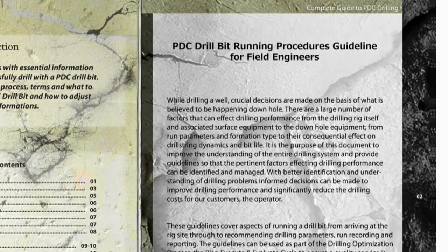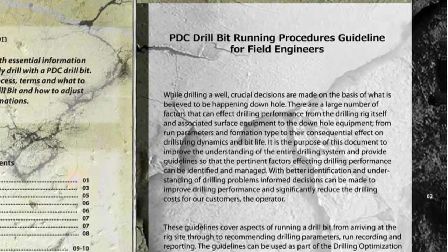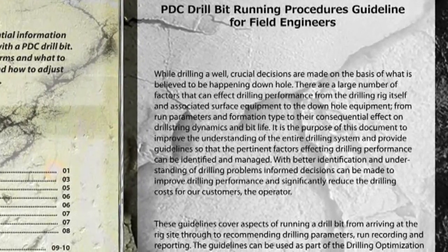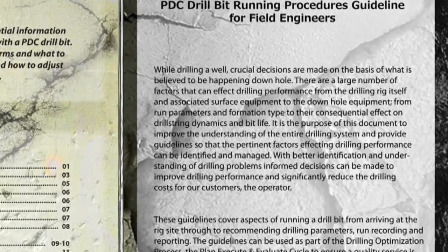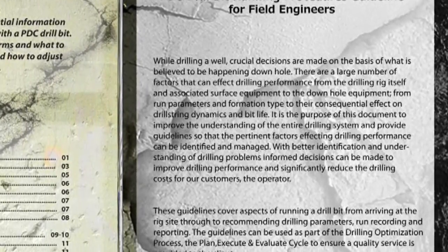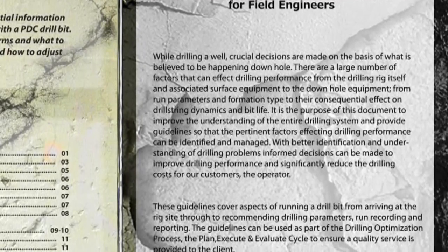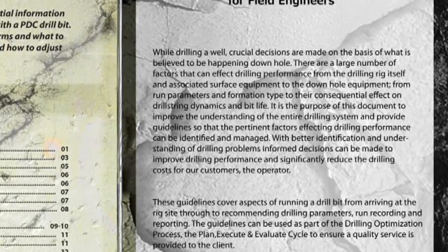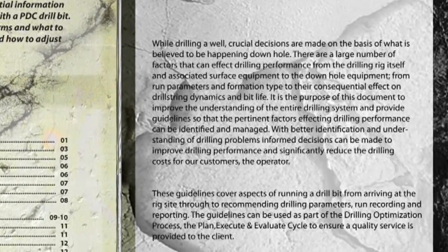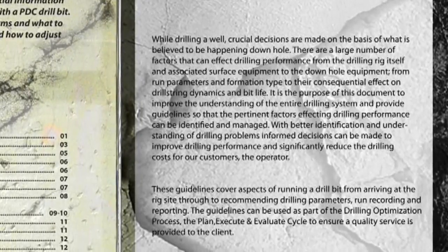PDC drill bit running procedures guideline for field engineers. While drilling a well, crucial decisions are made on the basis of what is believed to be happening downhole. There are a large number of factors that can affect drilling performance, from the drilling rig itself and associated surface equipment to the downhole equipment, from run parameters and formation type to their consequential effect on drill string dynamics and